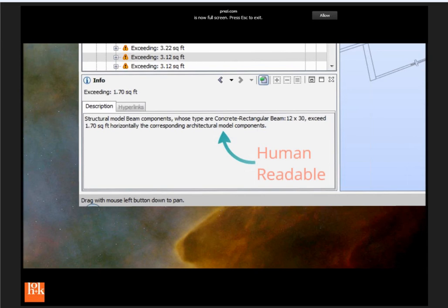One of the hardest problems I always had in Navisworks, and they are addressing this, is finding out where that clash actually is in the building, right? You can get a whole list of clashes, but understanding where that is, especially on a large, complex project, we used to have to do a lot of hacks with getting grids in and levels and stuff like that. I understand 2013's come a long way from that, but this has always done it automatically. And what it does is it gives you the space. So it tells you it's in the ceiling of room 204. Go look there.